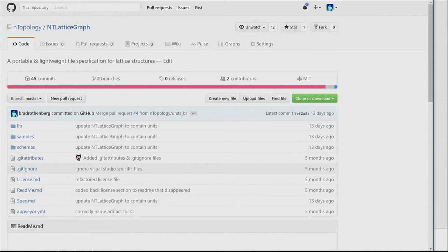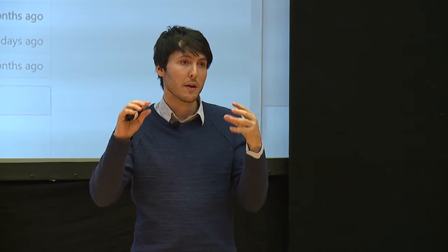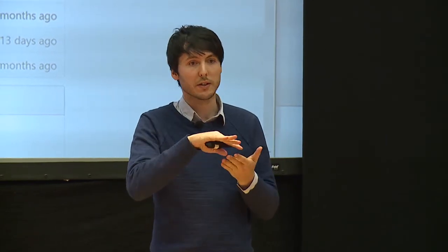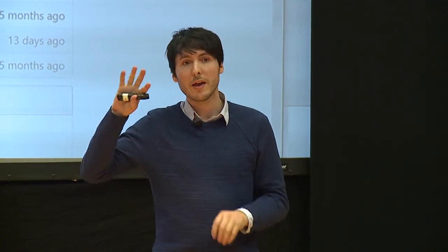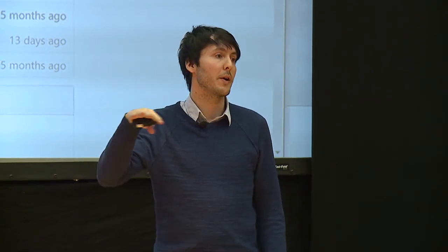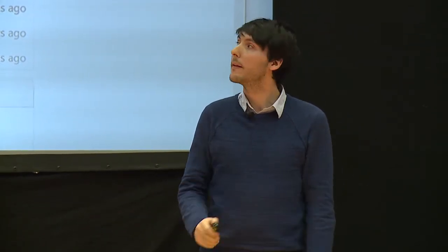And with that graph structure, we actually open sourced it as a file type. It's called LTCX. And we're trying to get this into 3MF. We've been going to the 3MF meetings. The goal is to use this really lightweight format to interface with both the simulation side and the build processing side. Because if you know what the topology is, it's much easier to slice that, and it's much easier to run a simulation on that. You don't have to make assumptions about the topology from an STL or do any complex intersection checking.